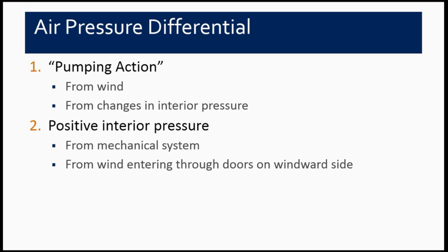But to get actual positive pressure to cause a problem, and we'll talk about this a little more in a few seconds, you need an airflow path. Just because the building's under positive pressure, if the roof inflates and stays inflated, you're not going to have a problem, because whatever moisture is in that air is going to condense out once, and then it's only by vapor diffusion that it's going to gradually get in there, but there's not a lot of airflow. And the steel deck actually does make a pretty darn good vapor retarder, not a good air barrier, but a pretty darn good vapor retarder. So as long as you aren't getting airflow, you're not going to get a lot of problems.